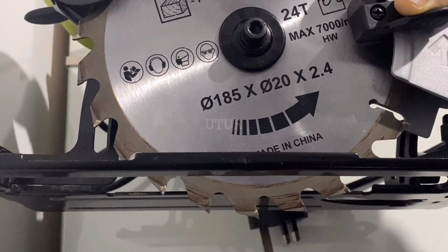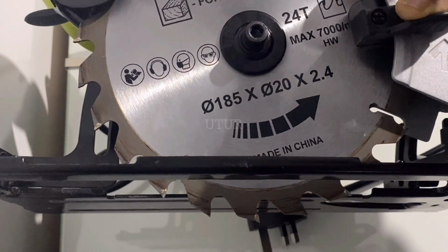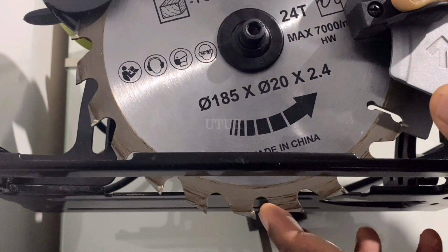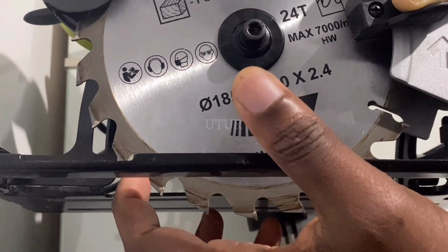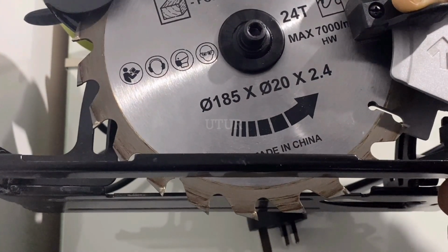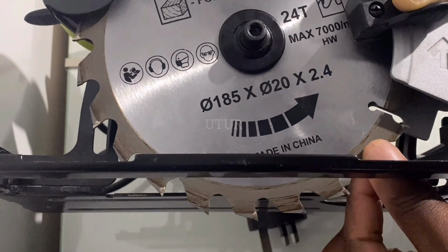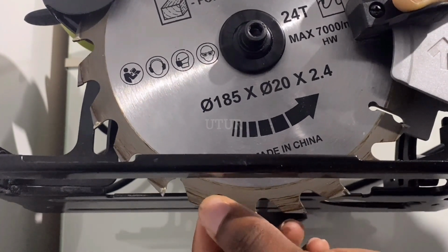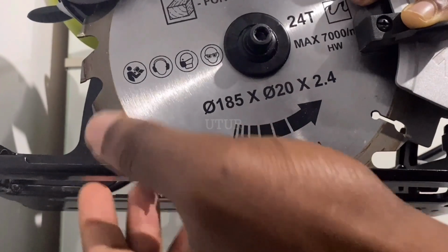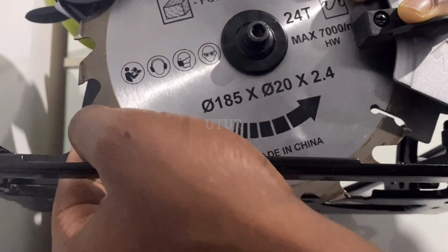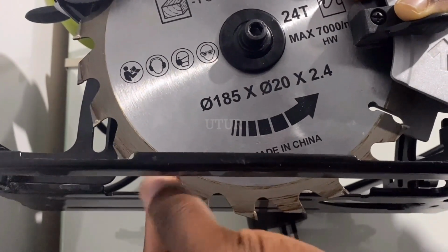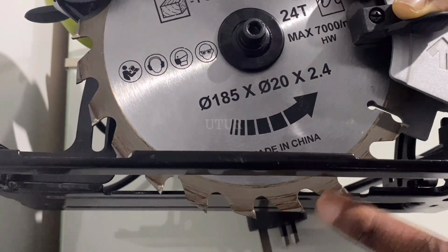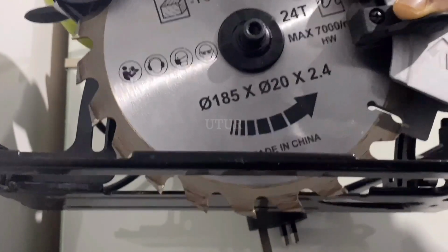And so your composite blades, or your combination or general purpose blade, will do a pretty good job of ripping and cross-cutting at the same time. So, what quality of cut can we expect if we proceed to utilize this ripping blade to cut strips from the hard plywood? I'd be expecting a somewhat poor quality cut, with excessive tear out in certain places. I would also be expecting overheating, okay?